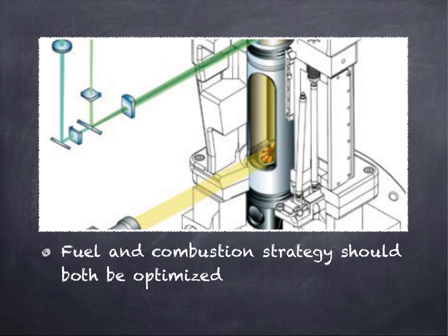a parameter space will require new conceptual and algorithmic methods for data analysis and automated recognition of large-scale property correlations. Adaptive learning algorithms and automatic optimization tools may provide a means to control real engines based on end product metrics of performance, efficiency, and emissions. The control history of such an engine provides data on a response function connecting a chosen, not necessarily optimal, set of sensor inputs and a set of available control parameters.